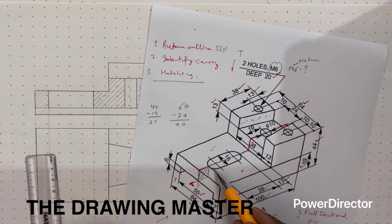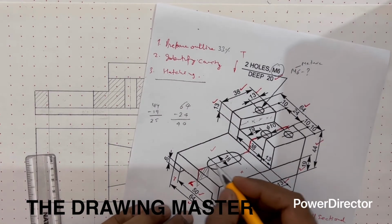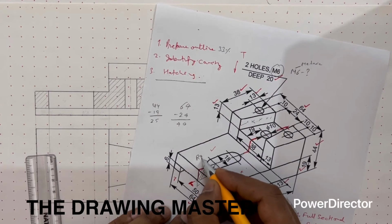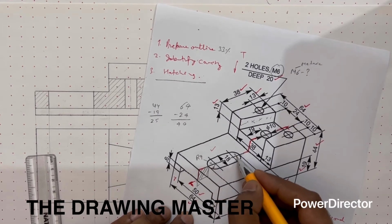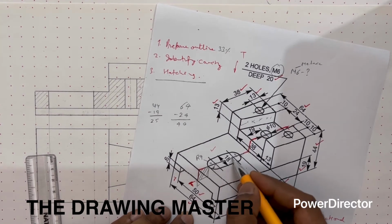So here two semicircles are there. This is 18, so let's calculate this dimension. If this dimension is 18, this dimension will be 9. So this radius is 9. R9 means radius is 9. So out of 38, this one is 9, this is 9. So this remaining dimension will be 20 mm.